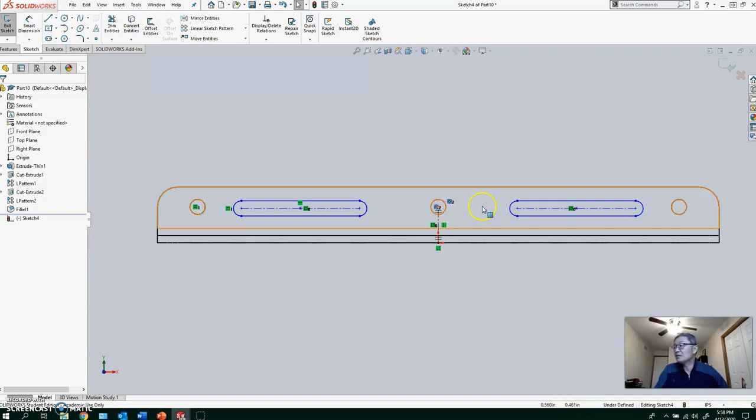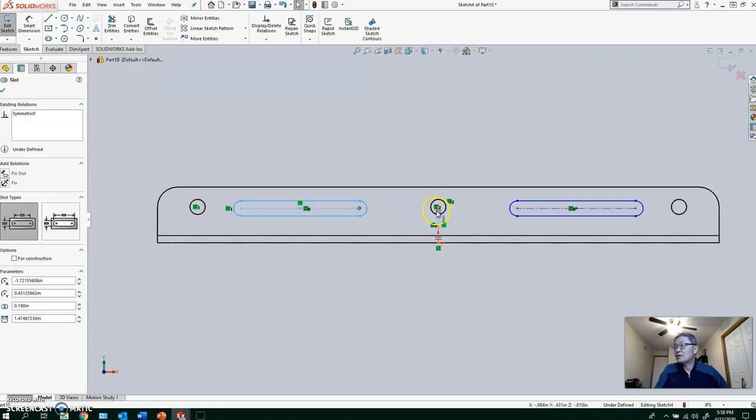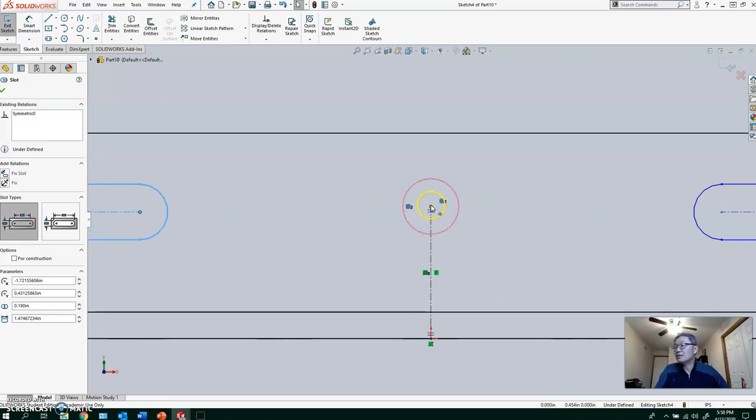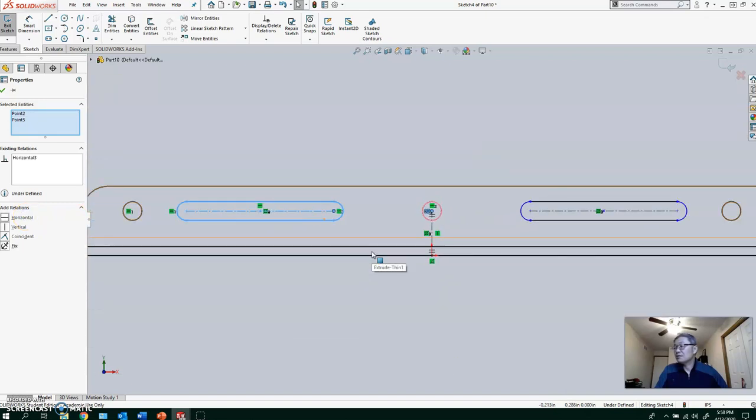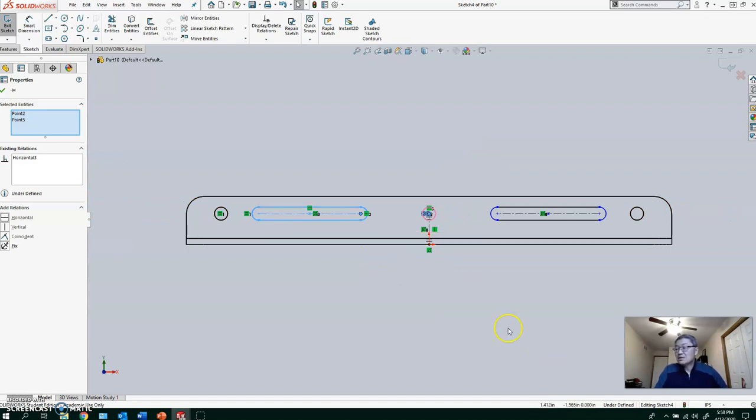Make a click. No, let's do it the other way. Okay, click the center of this one. Hit control. Click the center of this one. The end point of this one. No, did not get that one. Let me zoom in. Okay, now we have 2 points. Now I'm going to choose make horizontal. So now we make this one and the same line at the same horizontal level.